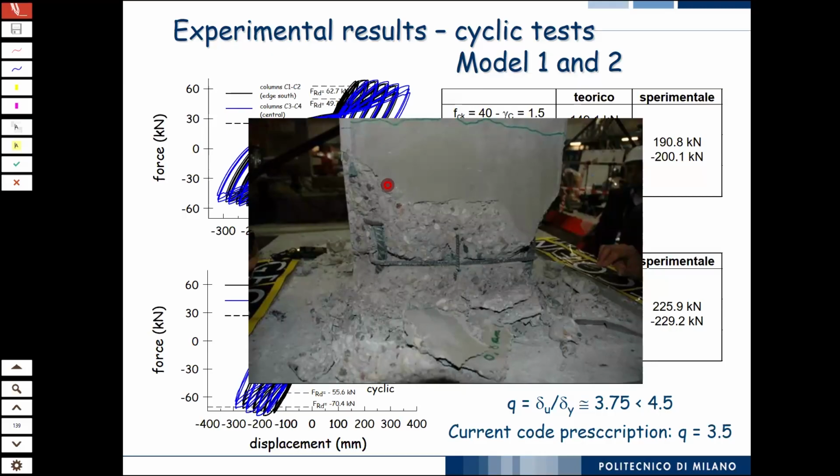But can you appreciate that that bar is a little bit curved? In between the two stirrups, when you expel the cover, that bar is like a beam pinned at its edges, which can buckle, and that it does. That was immediately outside the footing.